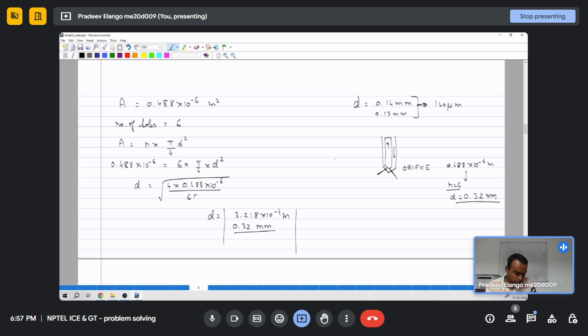So a regular diesel injector will have, say, a needle like this, and there will be a projection at some point, and this will be the outer body, and fuel comes to this cavity using another passage, and this will be under spring action.